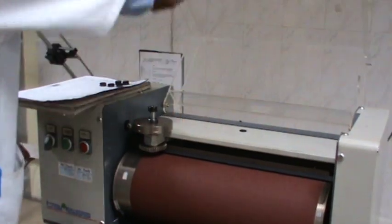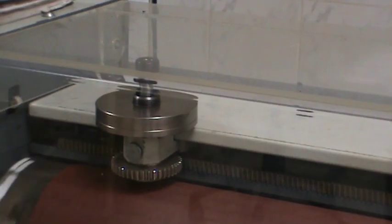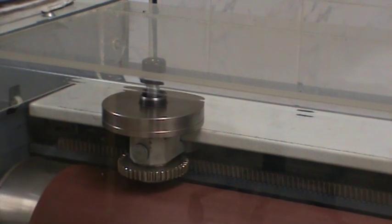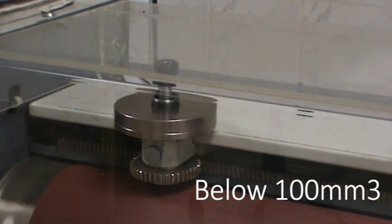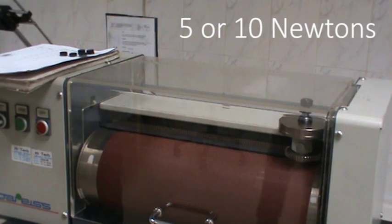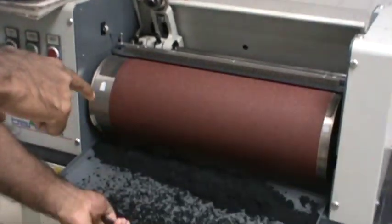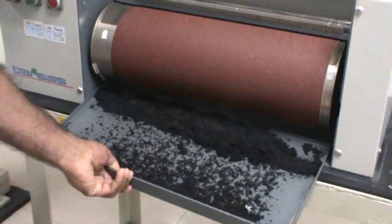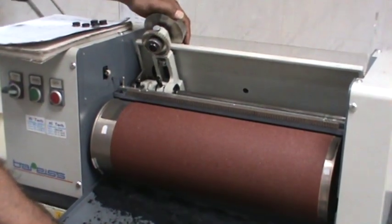It is desirable to have a lower abrasion loss reading, particularly where the rubber is in high abrasive applications. Highly abrasion-resistant compounds will have results below 100 millimetres cubed. It is important to note that the arm holding the rubber plug can weigh 5 or 10 newtons, and this should be quoted when the test result is given. The typical test is conducted in dry conditions, and a separate test method is employed for wet abrasion testing.